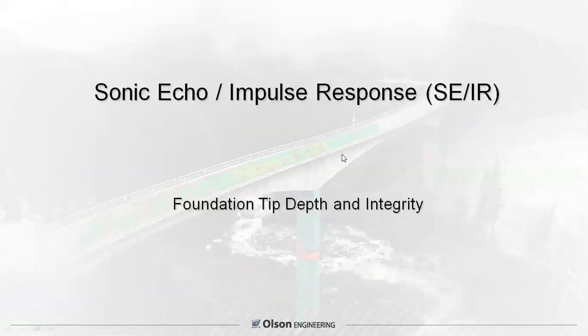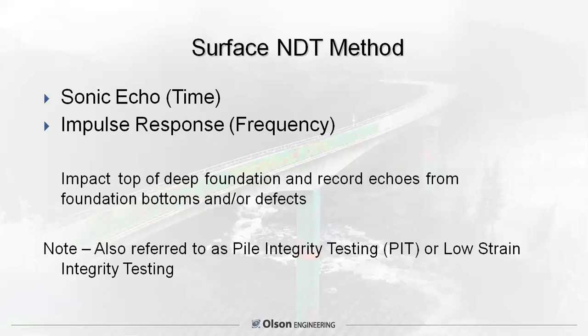So let's get into some of the individual test methods. We're going to start with what's probably the most common method for foundation evaluation, especially existing foundations. Sonic echo impulse response. Again, that's also called low strain integrity testing, also called pile integrity testing or PIT. There's a lot of different names for it. I've even heard it called impact echo from some DOTs. But it is used for foundation tip depth and integrity.